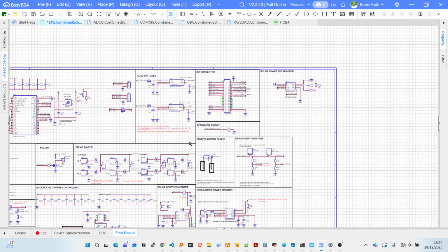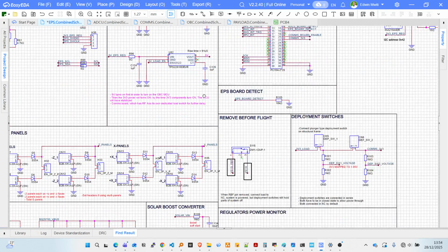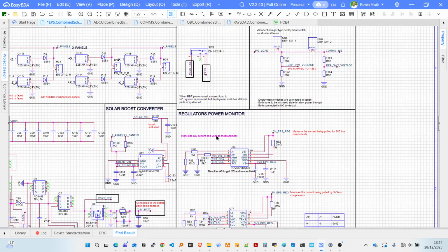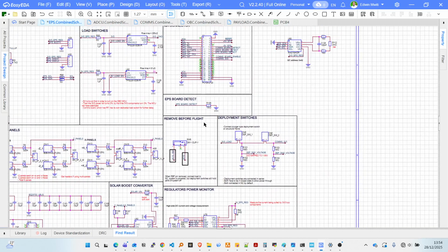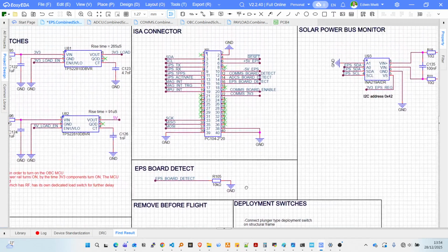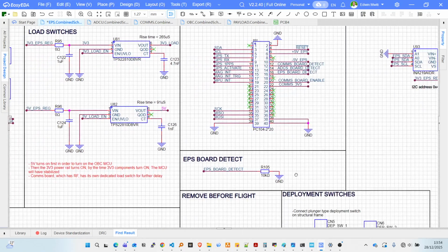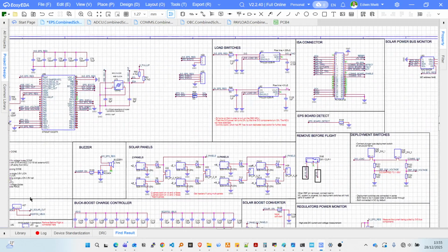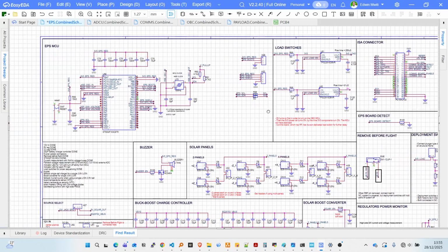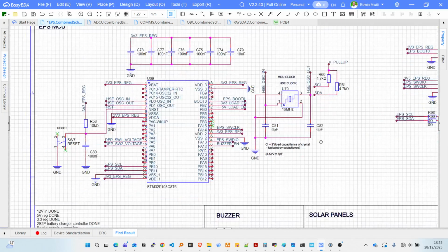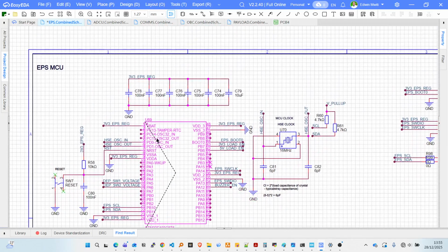Anyway, right. So from there, you have power supply to the loads, right? The next thing we need to do is monitor the voltages. We need data from this whole thing, right? We need to know what voltages we are reading from the solar, from the batteries, what current, what power, what is our consumption, etc. So the mother of all things is the MCU that will consolidate all that data.